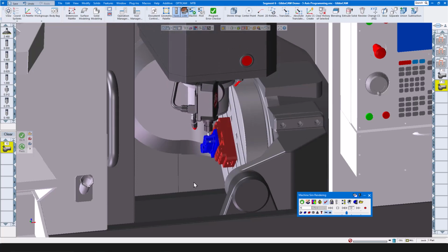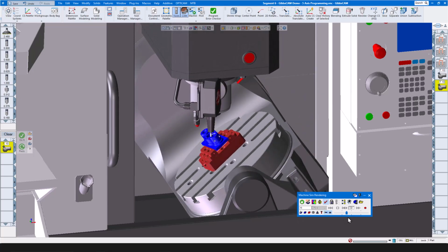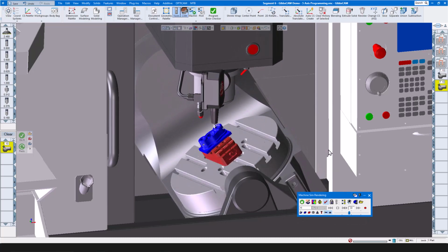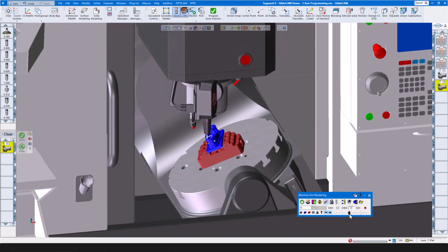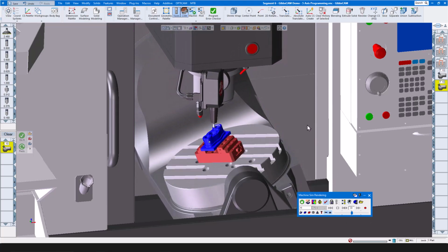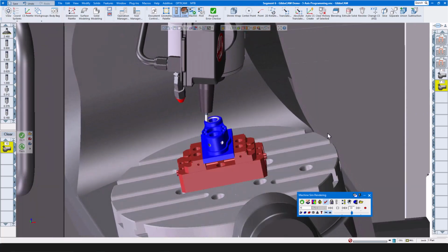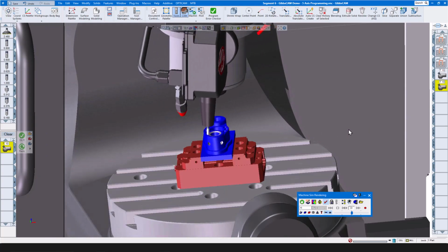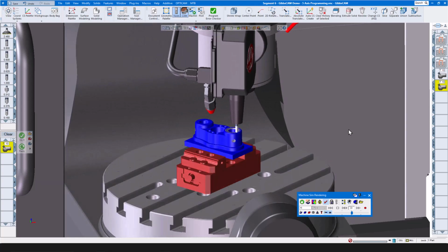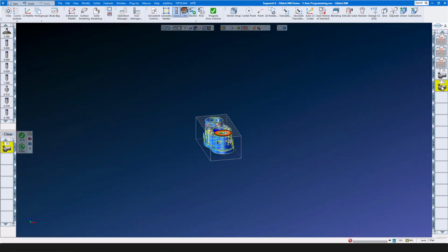As soon as we get to operation number 13, you will see the difference between 5-axis surfacing and 4-axis surfacing. Here in 5-axis, there is quite a bit of rotary movement while we're cutting this part. And if we want to switch to 4-axis and see a different type of movement, let's let this toolpath develop a little bit further while zooming in. And we can see the 5-axis machine maintaining the 8-degree tilt angle so that the cutter is actually doing some work. That's a lot of movement. Let's choke it down to 4-axis in the next operation.